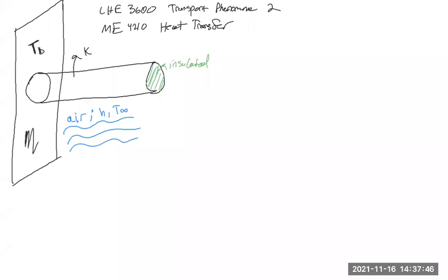So first, let's set up a coordinate system. In this kind of problem, this is usually a 1D heat transfer problem. We don't care about what's happening in the other directions. Here we have a cylindrical fin. I should have mentioned that. In cylindrical geometries, you have a z direction, a radial direction, and a theta or angular direction. Typically in fins, the direction that you care about is the one down the axis of the fin,